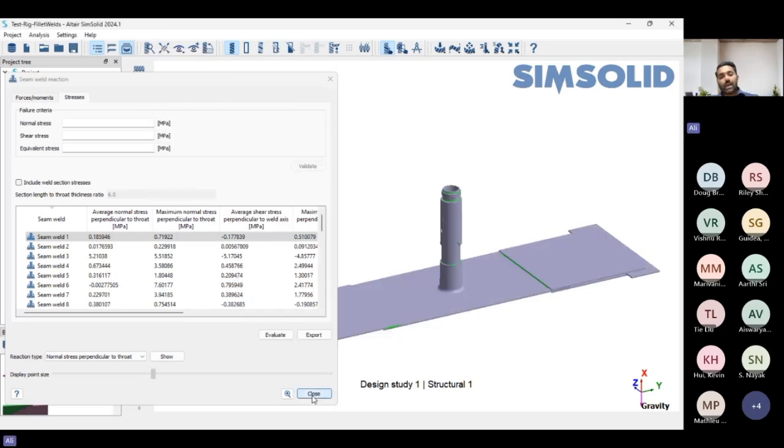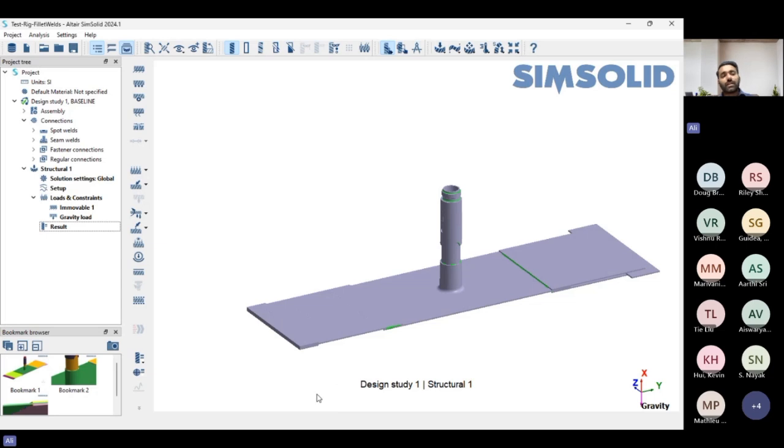Right. So as you see in here, it's a really easy interface that we have in SimSolid. It's quite intuitive. You have steps to follow and you get the results. Generally, you do not get stuck much, but again, there are some limitations. As one of the users asked, in case it's not able to detect, I can go back to my CAD assembly and create a weld from there itself, or I can just leave that as such and, for the time being, create those as bonded connections, right? So different kinds of things can be applied based on the problem statement that you have in your hand.